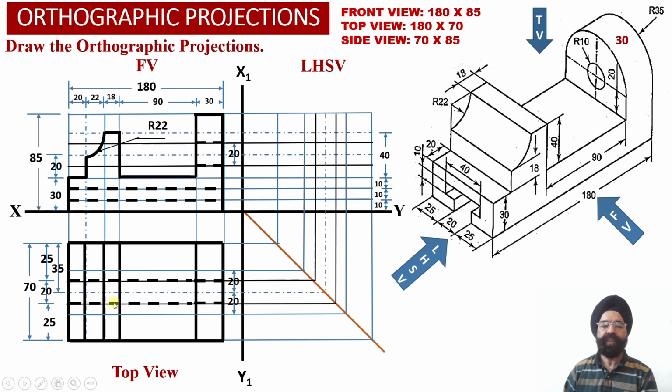So now once again, this top vertical surface and this top vertical surface corresponding to this T slot will also not be visible to the observer, as the observer is going to look at the solid from the top. So once again, another couple of dotted lines or hidden lines we are going to observe into the top view projections over here.